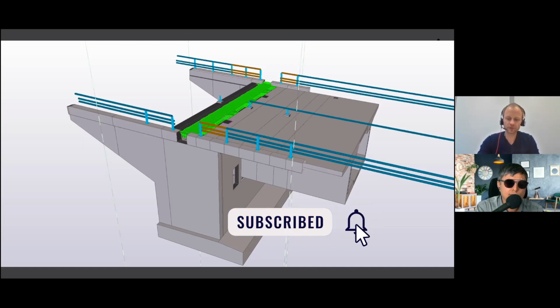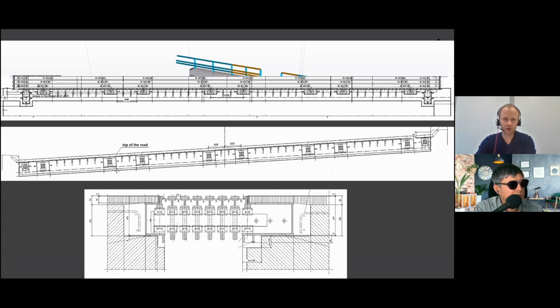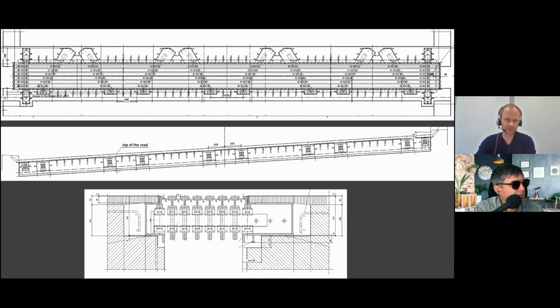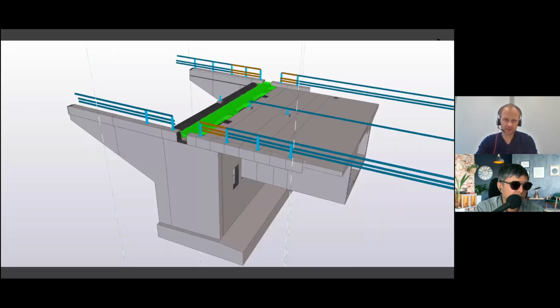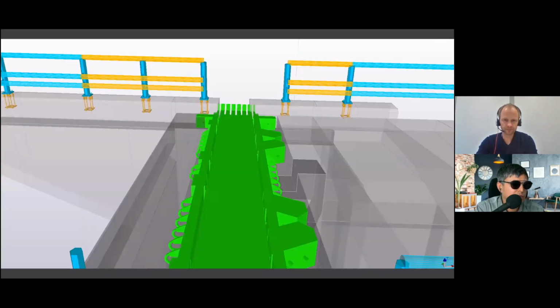We have a joint, and it's very important that a joint is fitted correctly. Normally you'd only have 2D drawings to do this, and in a complex structure where you have a lot of reinforcement as well, it's quite hard to foresee everything that might clash. So getting a good 3D model from the deliverer is very important. In this case, it's Maurer, and they've provided us with the IFC file. That's been very, very useful.